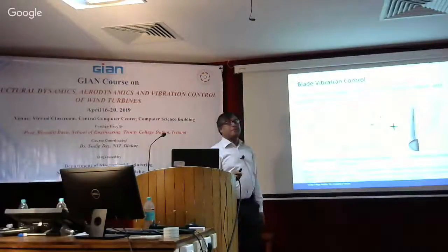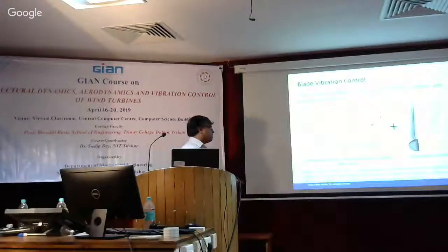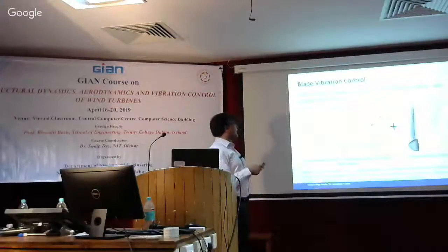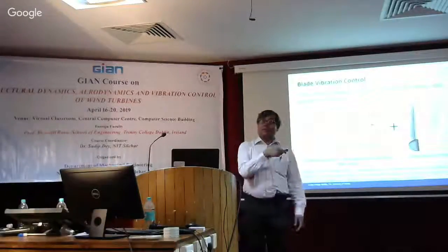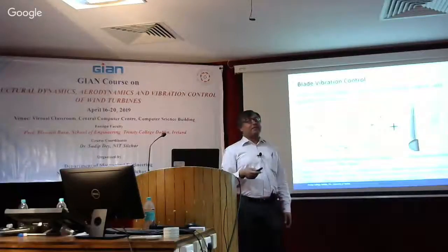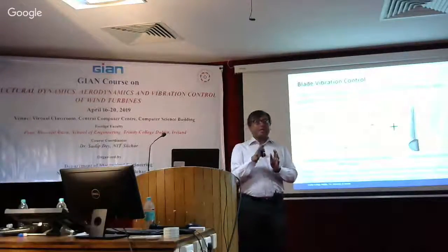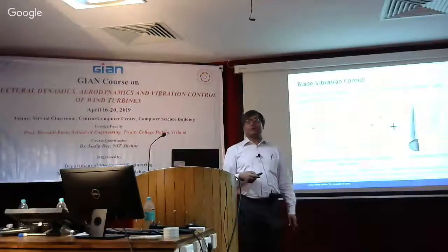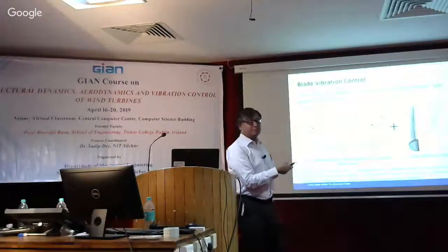I was mentioning decoupling the role of pitch and the vibration control. So this is a paper we published in the Royal Society journal, where we proposed a two-control strategy. In fact, what was done is we activated the pitch, but also the active tendon control was used as well. The active tendon control was used mainly to control the vibration, whereas the pitch was mainly used to control the power. That way we could reduce the demand on the pitch, but also the demand on the actuating force on the cable as well. So it's a kind of win-win situation. And in fact, it led to a Pareto-optimal optimization problem in this case.